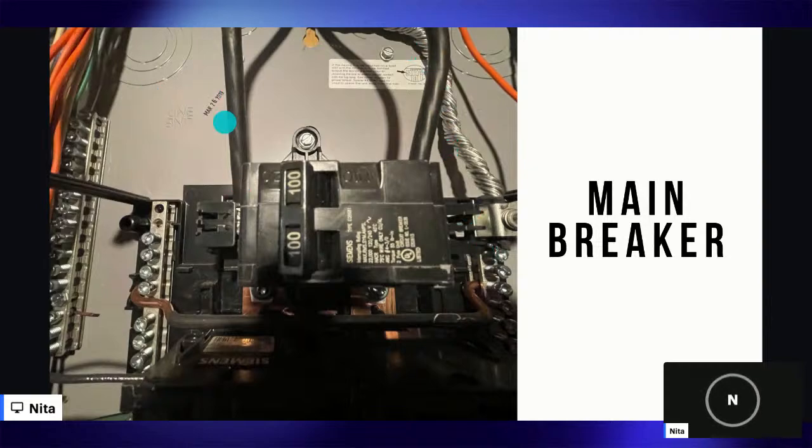We just learned the path. So when we say they come into the box to the service equipment, this is what we mean. They connect right here. Before we brought these two conductors in, this panel was not energized. Now it is hot. We are bringing in the power. So even if you turn off this main disconnect, these conductors are still hot, because they're getting their power from the transformer.